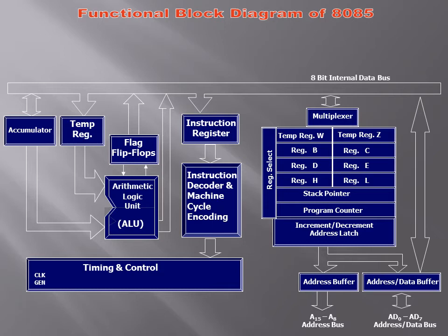So there is a control unit in the microprocessor, and in the control unit we have different sections. We have a clock generation section, in which we have two quartz crystal connections, X1 and X2. Then we have a clock out signal which is given to other devices outside the microprocessor, and then we have the control signals.